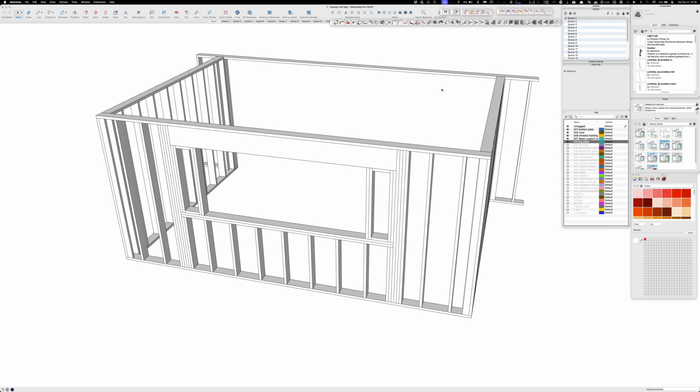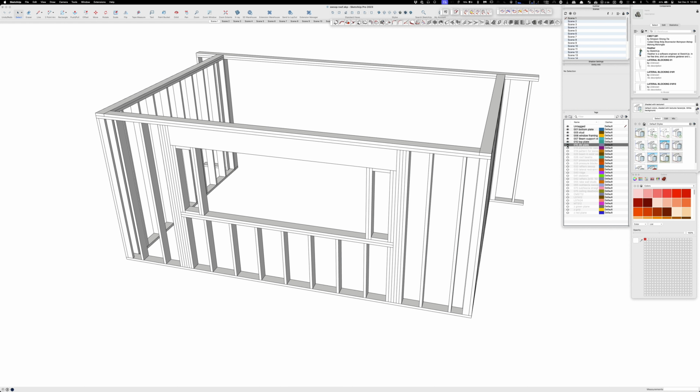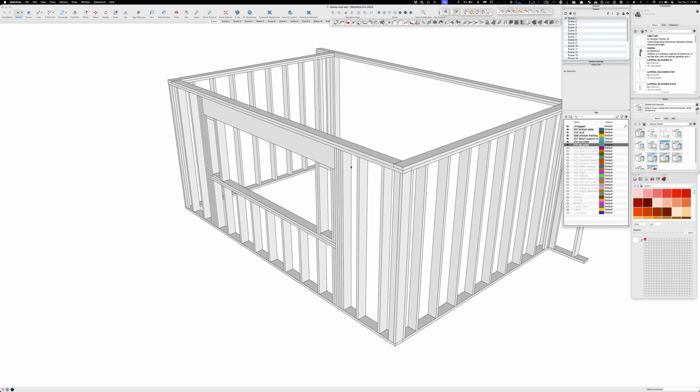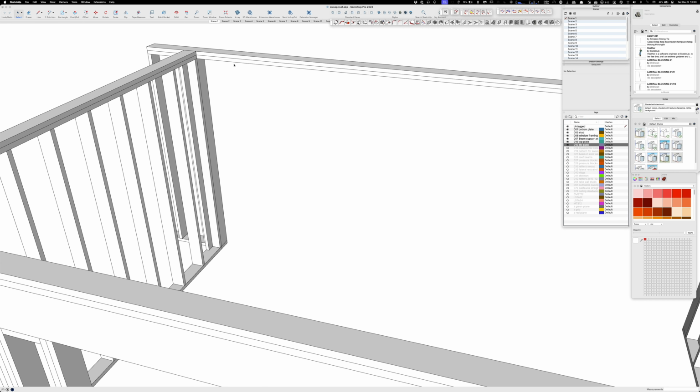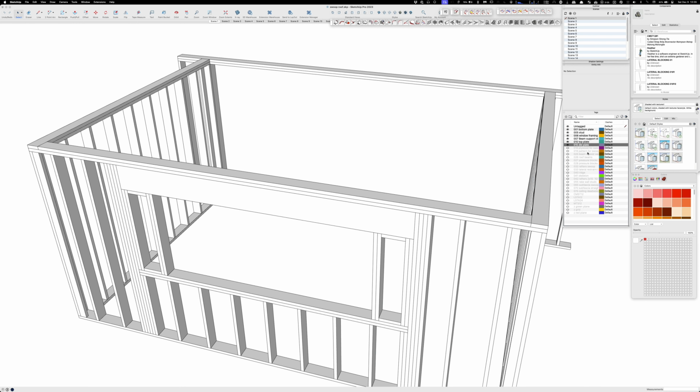There's the top plate, and in the framing world, there's even different terminology. I was always taught bottom plate, top plate. Those two plates get layouts so that you can build walls. And then the plate that goes on top of that, we call that the double plate. And its sole purpose in life is just to tie together connections. Like if this top plate was longer than a single plate, and it was two pieces, then you would use a double plate to splice over the connection. This wall in the back is the existing wall, and that's why you see it's drawn like that, but you could always overlap it. It would be stronger if you did.